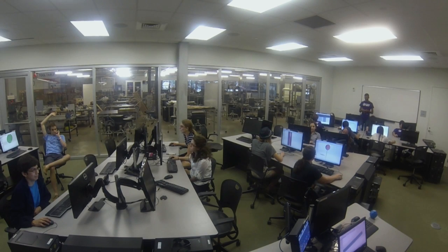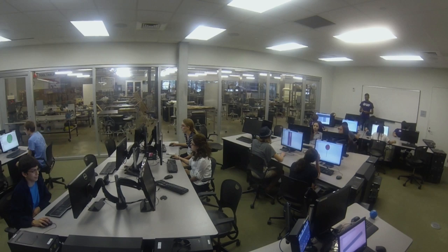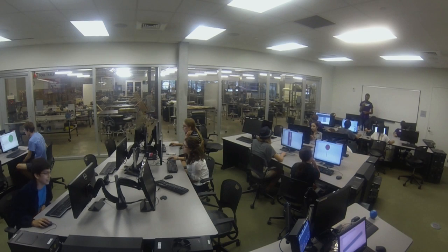That is an option for how to do it. Or I guess that is one way to do it. So you need to make a new reference plane somewhere in the middle of the light bulb, like dead center. Then you're going to need to use the revolve cut and cut out the other bits of it.